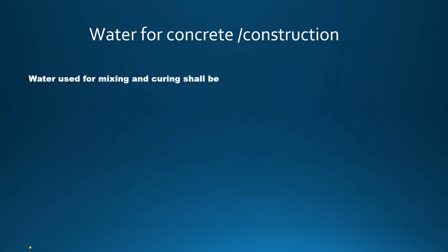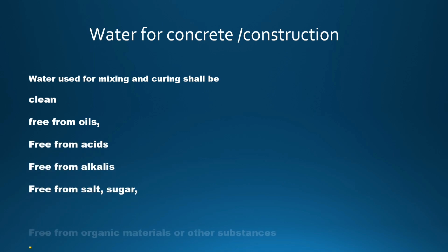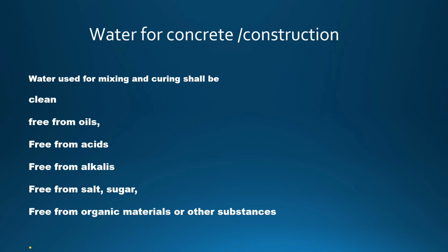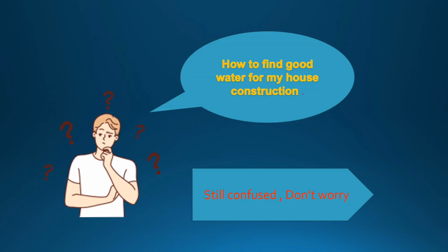The water used for concrete mixing and curing shall be clean, free from oils, free from acids, free from alkalis, free from salt, sugar, free from organic materials or any other substances that may be deleterious to the concrete or steel. The presence of all these materials will affect the strength of the concrete and will also lead to the corrosion of the steel reinforcement which we are using inside the concrete. Still confused? Don't worry, we will find out.